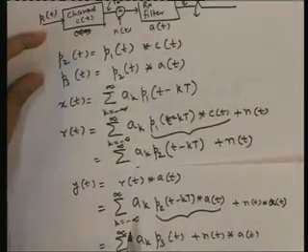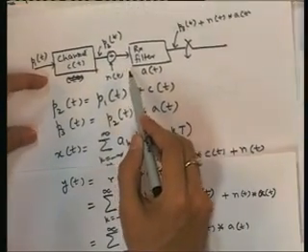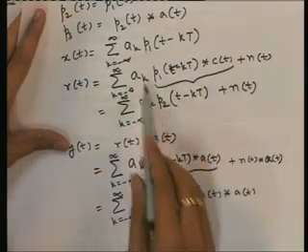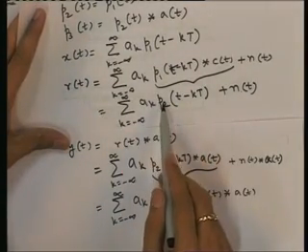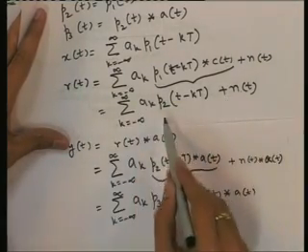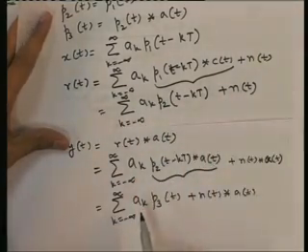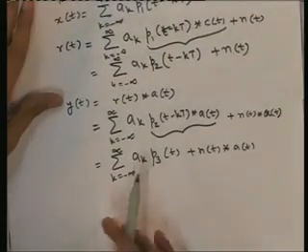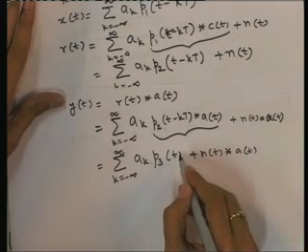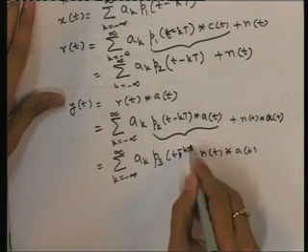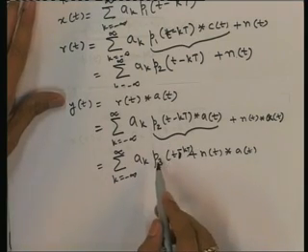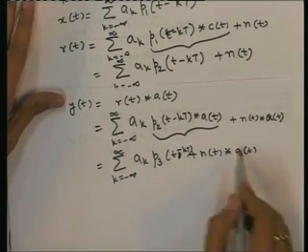Then what we receive, r(t), is this convolution, and this we have brought to this form. This is p2 shifted, so it is like a PAM signal with this pulse plus some noise, and after the receive filter what we have got is again like a PAM signal, with p3(t minus kT),